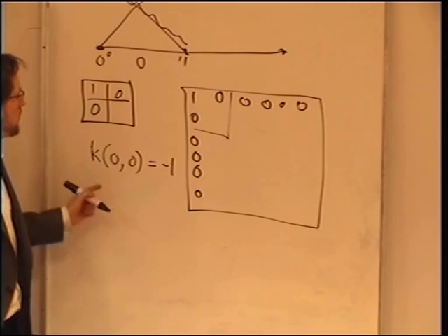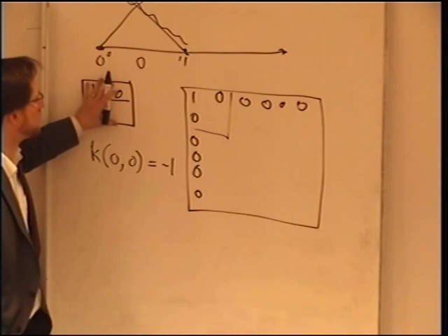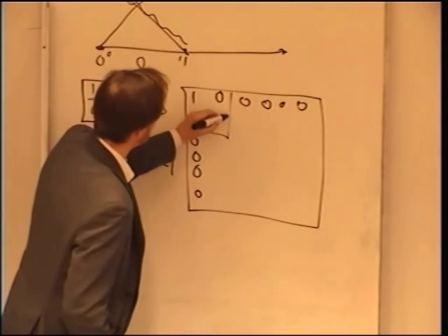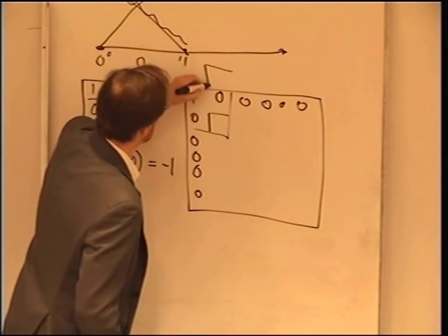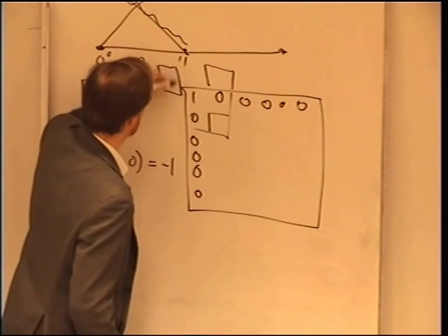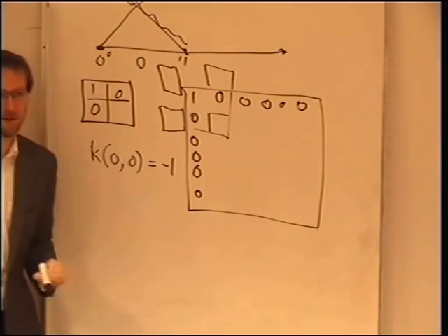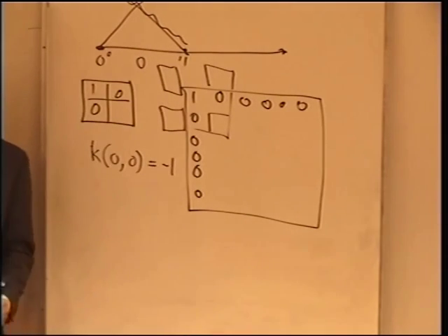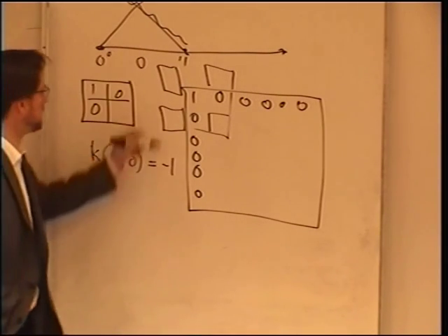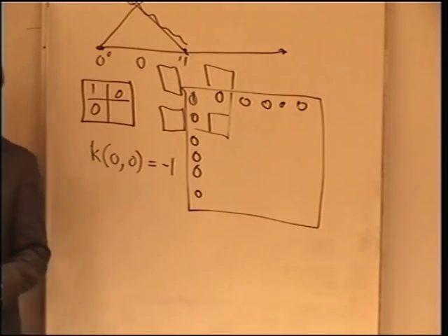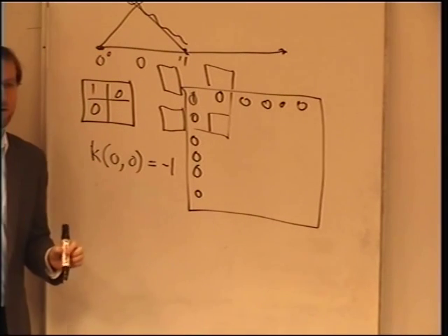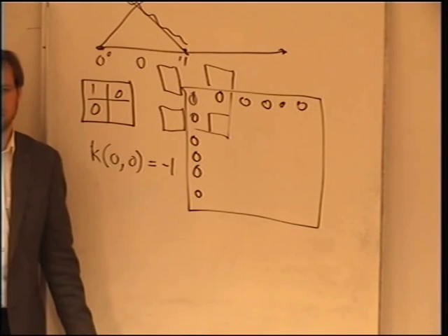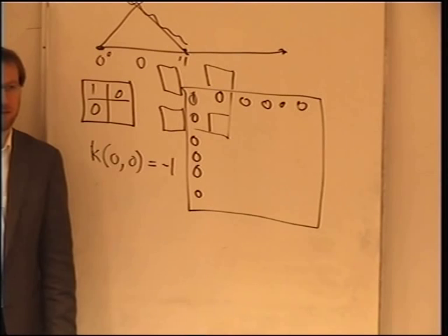And so when we do this, what happens is we take this small matrix and we put things in here, but we're actually asking it to insert into the block which looks like this. And so PETSc puts that value in correctly, and it throws away these three. And that's almost exactly what we wanted. The problem is that we now haven't added anything in there. And then afterwards we go through and we set the diagonal on all the boundary condition nodes to be 1, which is a straightforward process.